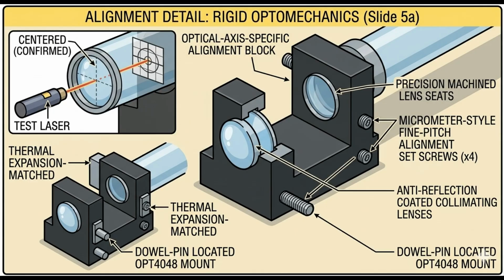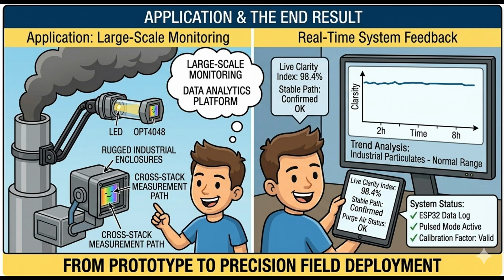When you're setting up a transmissometer, you're going to have to deal with alignment. And the smaller they are, the easier they are to align. The materials you use, they're heating up like a chimney, I didn't want to use sheet metal because it would change shape. I used rigid aluminum. And the longer you get, you have to make sure things stay in line. For example, if it moves during your measurement period, it's going to change your data, and you want to be able to say, hey, everything stayed aligned during my sampling period. Therefore, the only change is in the air or water in between the two measurement points.